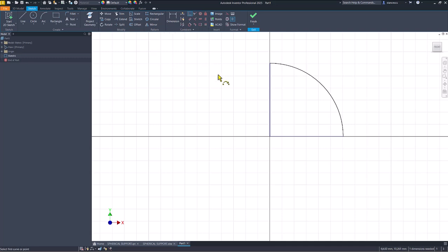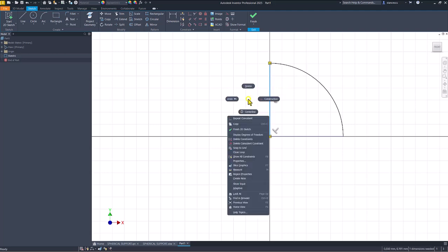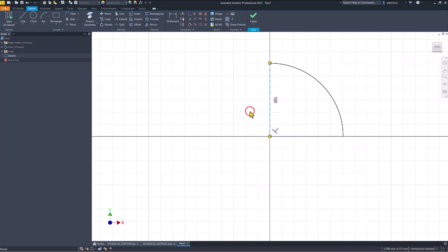We apply escape, we select this, and we can either select center line from here or from here. It is better to select here, but take care, because only when you select a line in a sketch is this possible. Center line, we place the radius of 30,